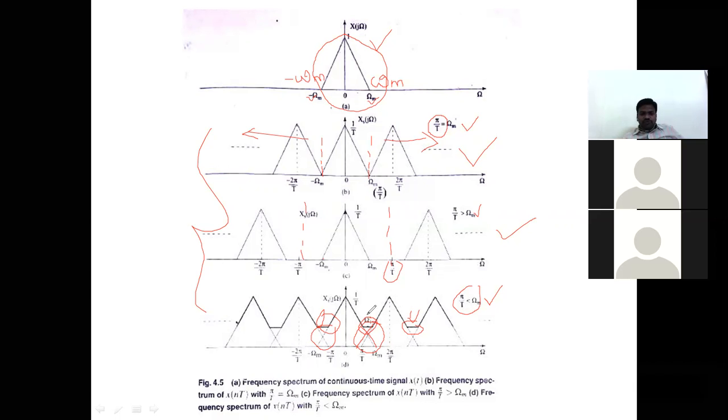Okay. Now case one, case two, case three. So this is about the sampling. I require 2 more classes to complete this chapter. That's all for today, and I will give you some time for noting or drawing. Just draw the waveforms: case one, case two, case three. In case three, obviously there is an overlapping of the samples. Whenever overlapping occurs, we cannot get the original data, or regenerate the original data from the sampled sequence. So always select proper values for the sampling frequency. That must be greater than or equal to 2 Fm, twice the maximum frequency component in the given signal, right?